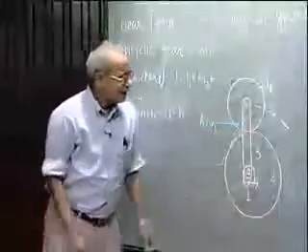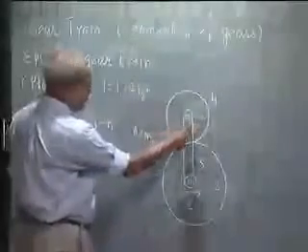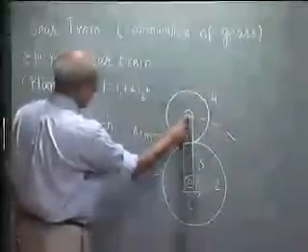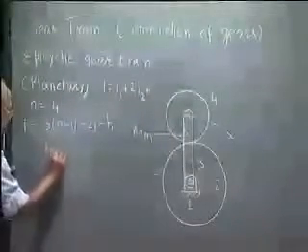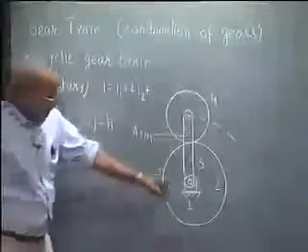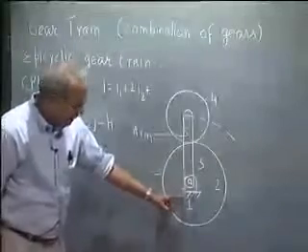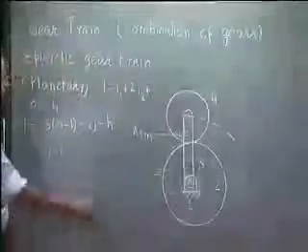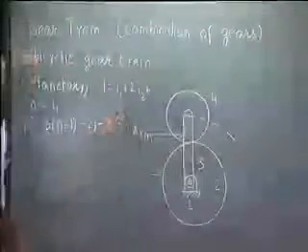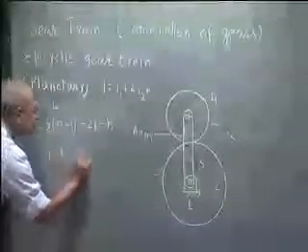Now here, there is a revolute pair between the arm and gear 4, so j1 is 1. Here is a revolute pair, but that connects 3 links, namely 1, 2 and 3. So this is a hinge of type J2. So J2 is also 1.